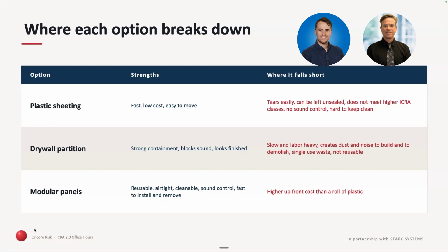The drywall partitions, I still see that done a lot, and I don't like it because contractors don't understand that they can't come in and cut the drywall right in the nurse's station or wherever else, and that's been a challenge. So we try to teach them that if you're going to do that type of situation, you need to make your cuts outside, tape them, and bring them in, and wipe down the product, which is another issue altogether with drywall. It doesn't easily clean. And then we have some of the modular panels.